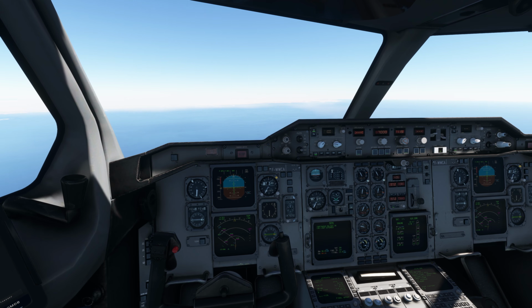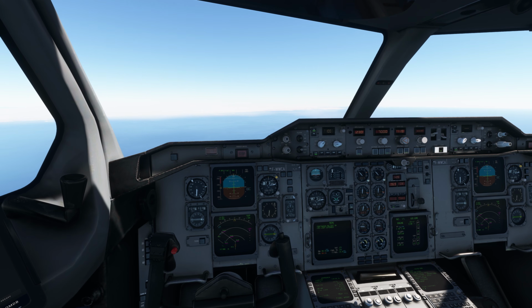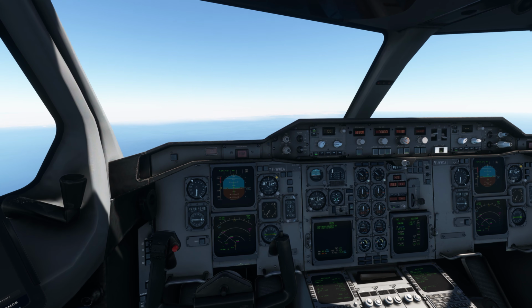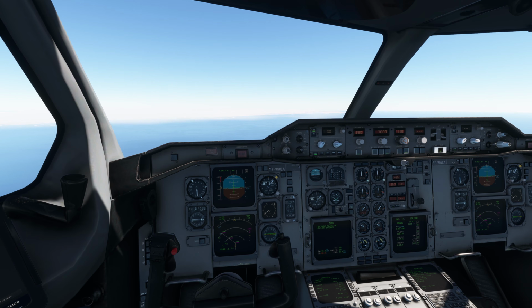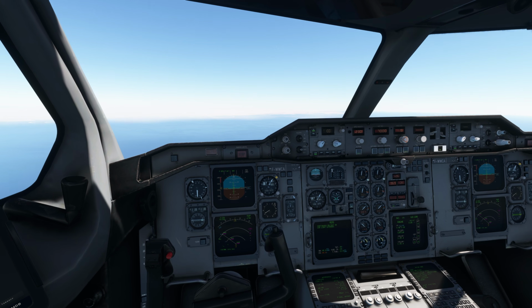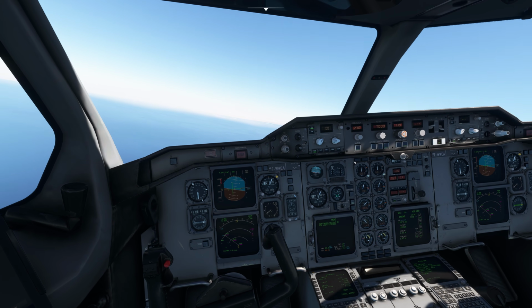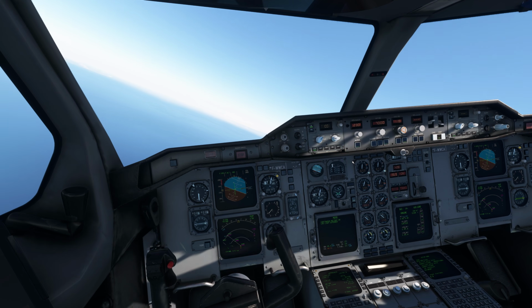So the basic purpose of setting the minimums is to basically look at the runway. If the autopilot hasn't aligned the plane with the runway, or you're not going to touch the runway at the right point, then at any time you can perform a go around, or call it a missed approach. Because it's a precision approach, it's very precise, but obviously it also depends upon the GPS signals your plane is getting. And if it's not following the glide slope properly, or if it's not following the lateral alignment or the horizontal alignment, then obviously you have to do something about that. So that's why at the minimum altitude, you look at the runway.